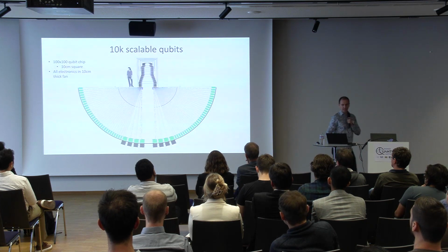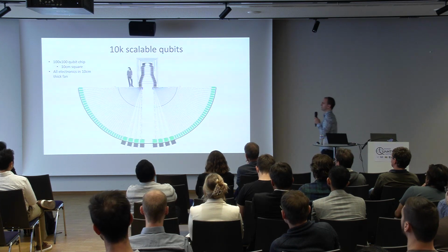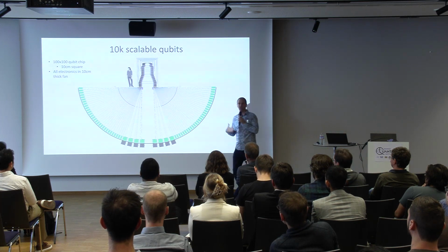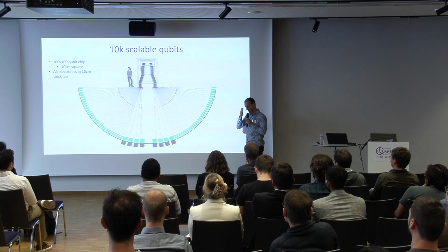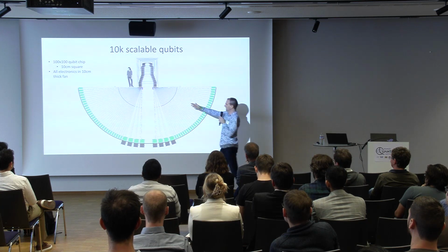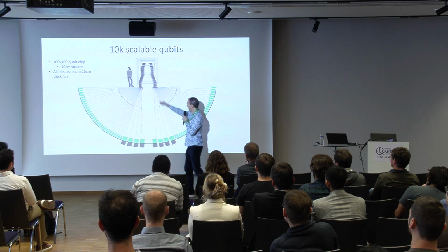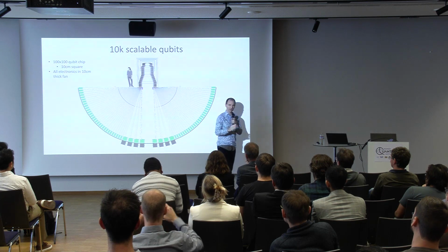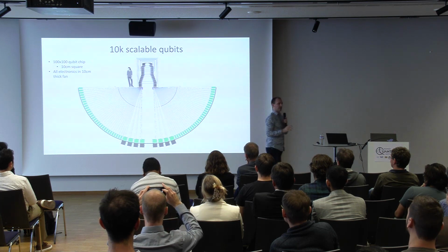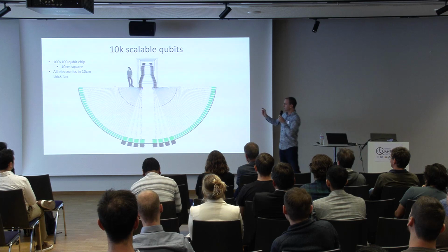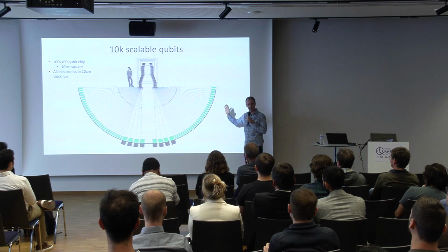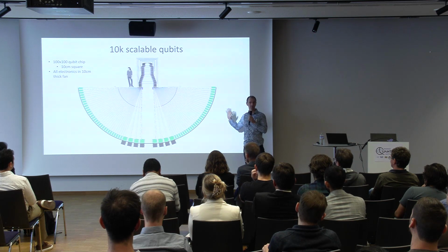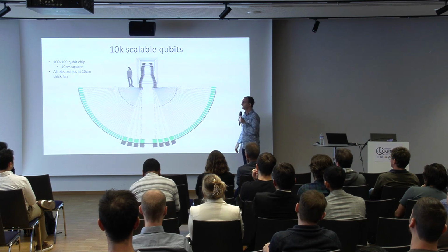And just to give a little bit more insight into what it means, what would a tileable module mean? So this is 10,000 qubits, where you've done the following thought exercise. You've had to think, all right, a qubit needs amplifiers, needs wiring, needs control electronics, needs classical compute. Take all of that hardware and arrange it in a fan the same thickness as your patch of qubits. So we're assuming 10,000 qubits, 10 by 10 centimeters. Each qubit is a square millimeter. So that's your 4 inches aside.